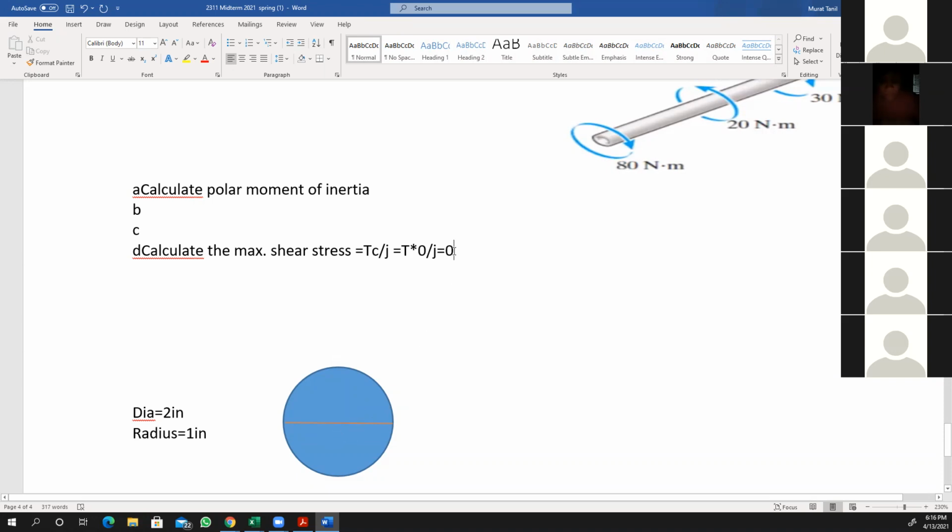That's 0. And I mentioned in class that if you go home and try to get spaghettis and rotate them, applying torque on one side, you will see that the spaghettis along the surface deform first, because maximum shear stress and maximum shear strain are developed at the outer surface as opposed to the inner surface. The inner portion is 0 at the neutral axis and it's experiencing less stress and goes through less deformation until failure.